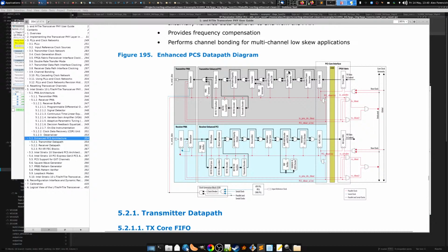And then you can go through various blocks to support various protocols. So this supports Interlaken. 64/66 is for 10 gigabit Ethernet. And then the scrambler is also used for 10 gigabit Ethernet. And then the Interlaken disparity generator, I guess, is for Interlaken. And then this goes through the gearbox and then out onto the wire. They also have some components for forward error correction: the transcode encoder, KR-FEC encoder, KR-FEC scrambler, and KR-FEC TX gearbox. So all this stuff is required for adding the FEC. And then that goes through the serializer and out onto the wire.